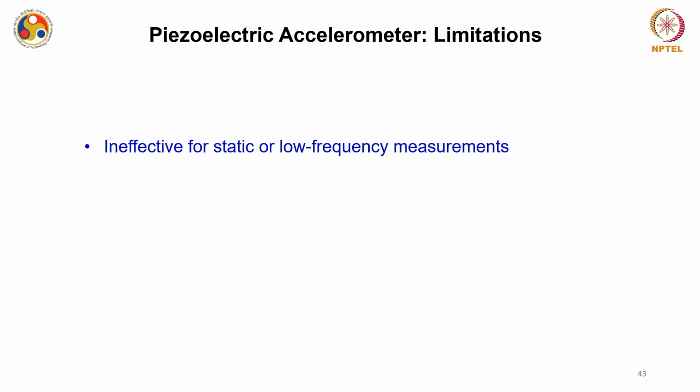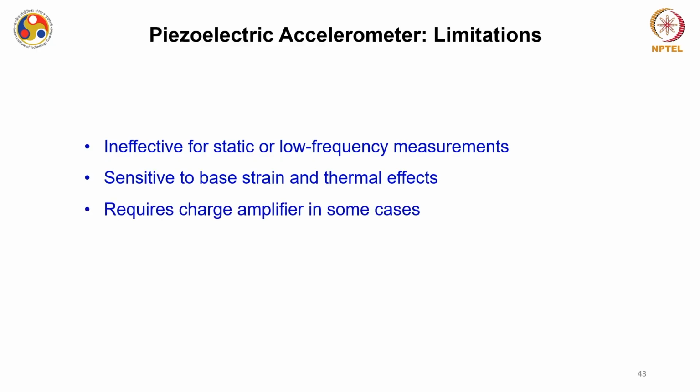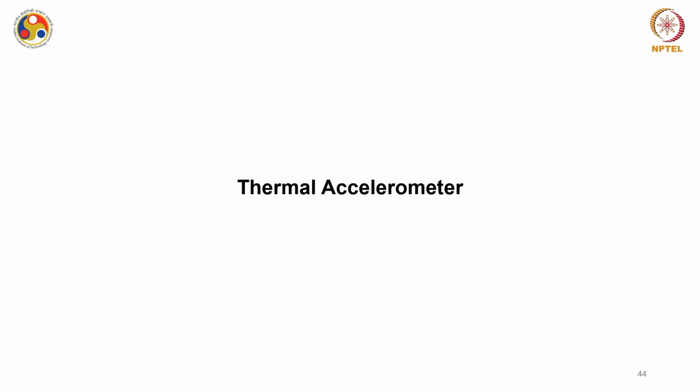However, there are certain limitations: they are ineffective for static or low frequency measurements, while they are sensitive to base strain and thermal effects. Certain kinds of piezoelectric accelerometers also require charge amplifiers, because the output is in the form of charges, and charge amplifiers are difficult to design.